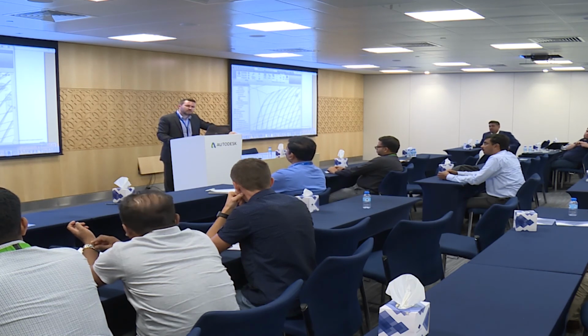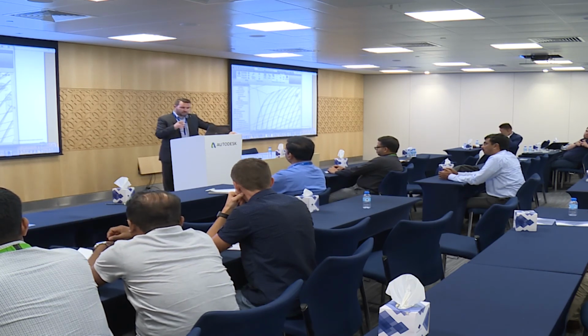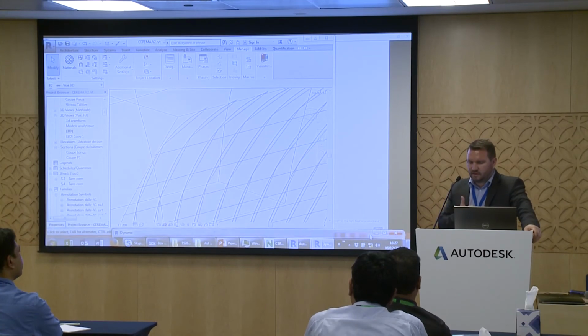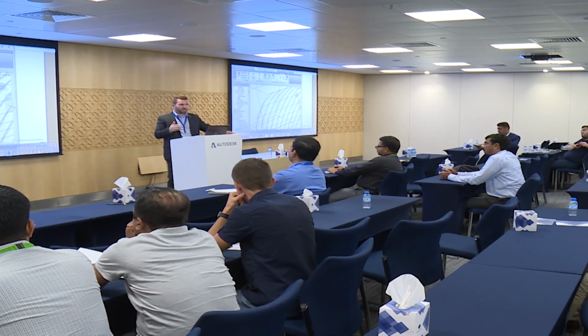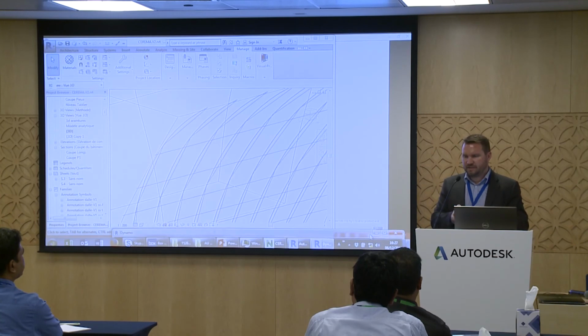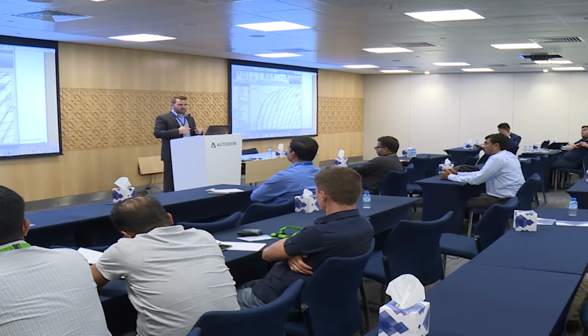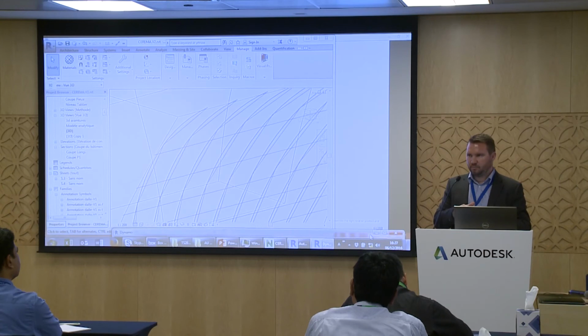To minimize the file size, in fact, what I say is you have to work with linked files for everything that you can split. It means that if you have, for example, a building, and in fact it's two buildings, A1, A2, so two files, and in the building there will be plumbing in one file, mechanical in another file, you see.